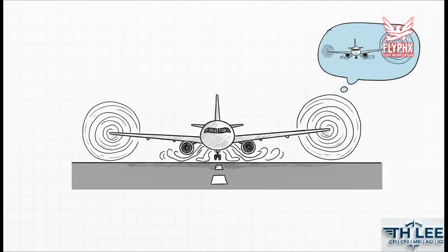Now picture this. What happens when we fly super close to the runway? We enter what's called ground effect. When you fly within about 1 wingspan's height of the ground, the solid Earth actually physically blocks those wingtip vortices from forming fully. And because those vortices are blocked, your induced drag drops significantly. With way less induced drag holding you back and pulling your lift vector backwards, your wing suddenly needs less total lift to maintain altitude. Your whole wing basically becomes hyper-efficient. That's why it feels like you're floating on a magical cushion of air right before you touch down.